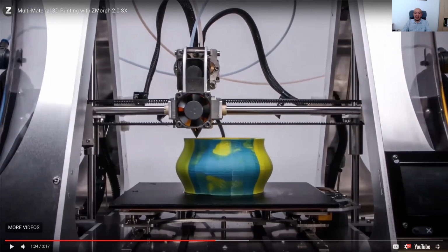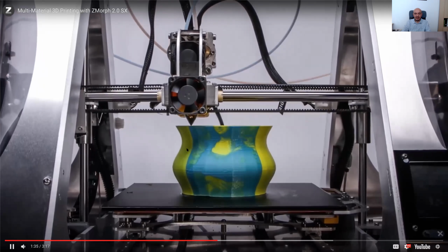So you see, they have a single nozzle, but the conventional two color or two nozzle FFF printers make use of two extruders. They have separate colors, and they simply, let's say, print the yellow part first, and then clean the nozzle, and then print the blue part with the other nozzle. But in their technology, they combine these filaments into a kind of chamber, and then try to adjust the color by their computational algorithm.